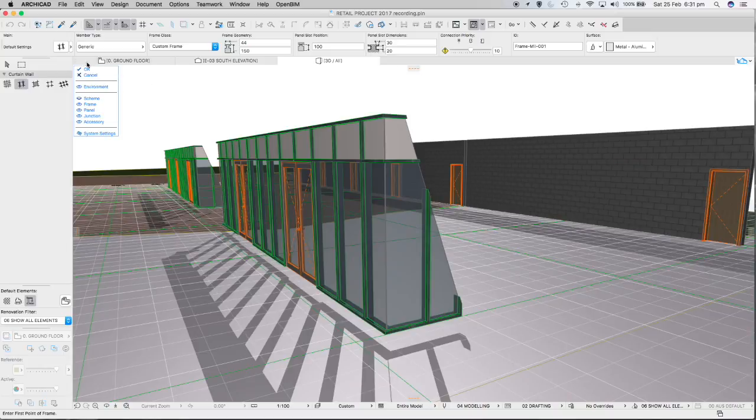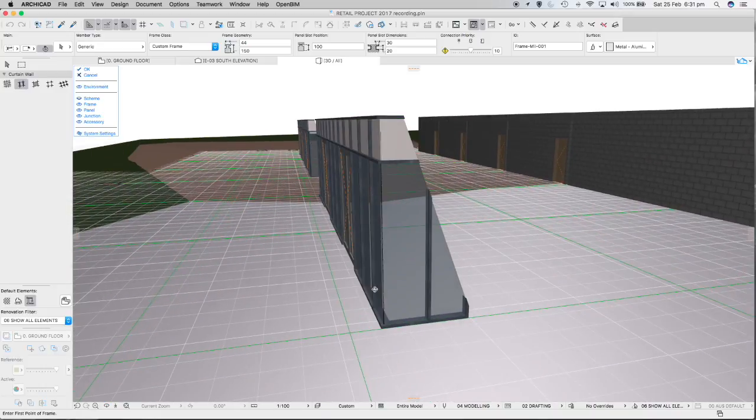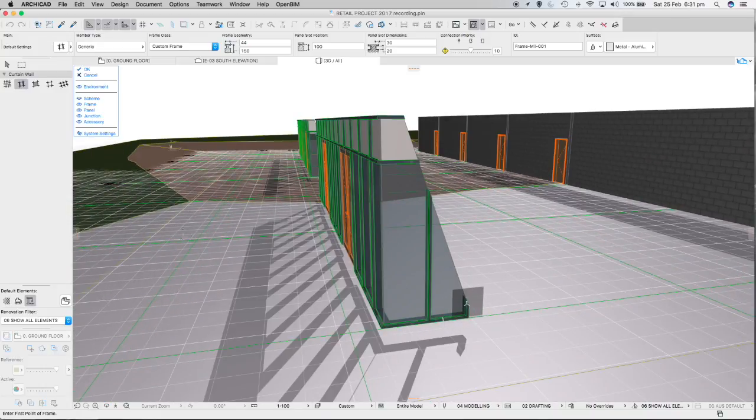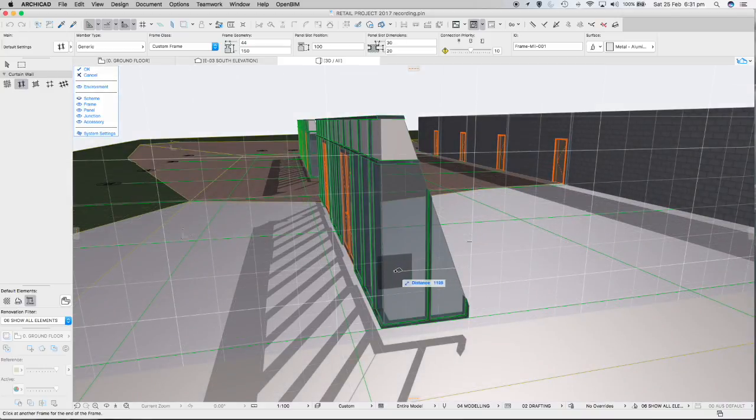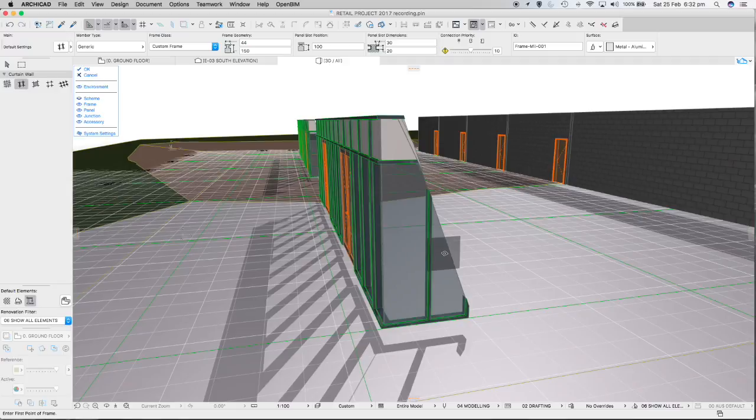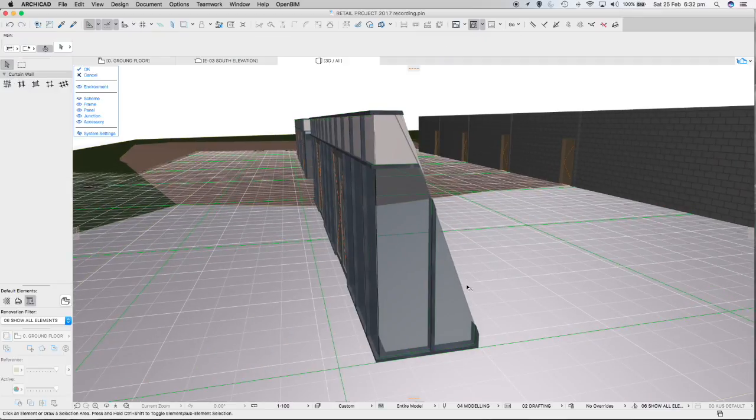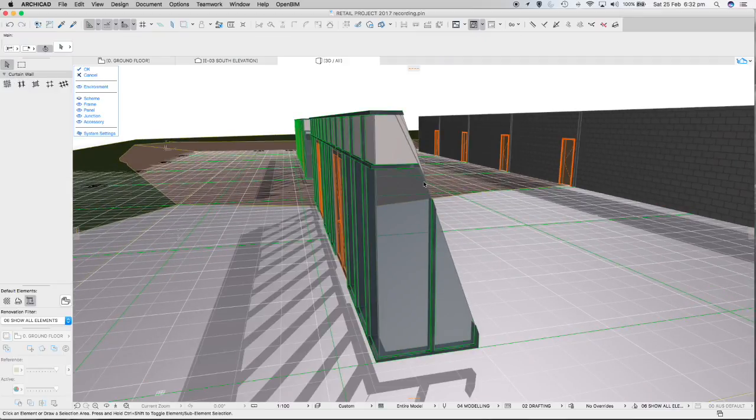When you're ready to do a bit of visualisation, you'll make sure you've got your colour scheme set up. But then when you've got that frame ready to go in, this curtain wall frame ready to go in, you can place new frames wherever you like. For example, I haven't found this terribly successful so far in picking the places we want to go to, but I've just placed a frame from somewhere along this invisible edge up here.